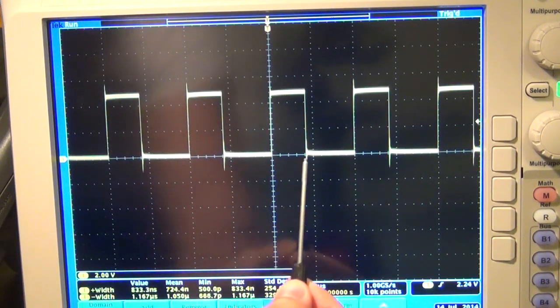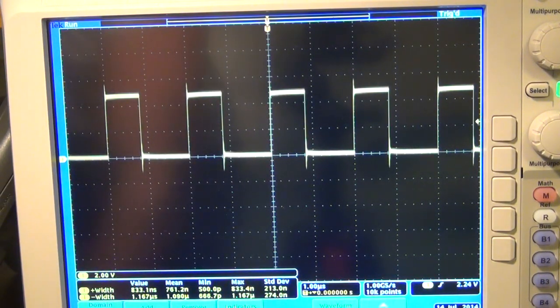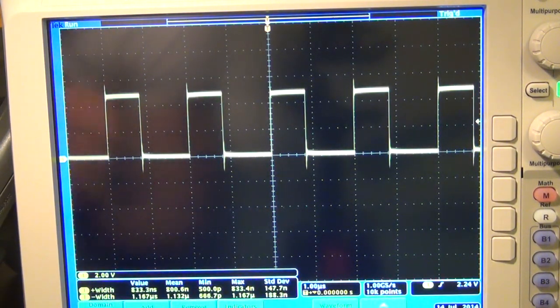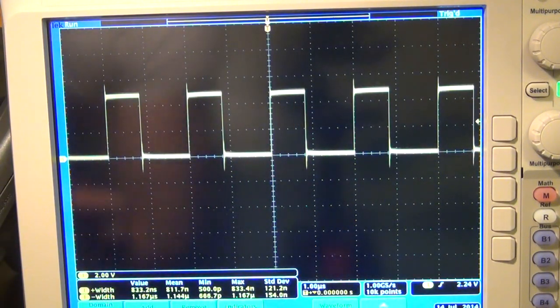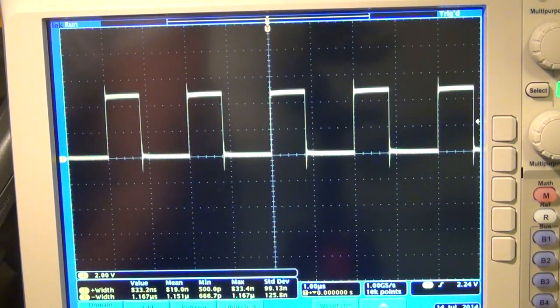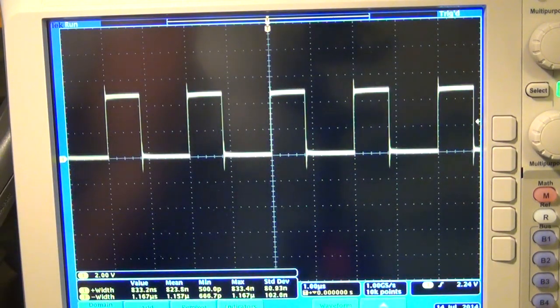It meets that. But the low, again, doesn't meet that. It's about 3 times longer than it should be. But it still works, and I don't know why. Like I said before, I think it's just because the only thing the IC inside the NeoPixel cares about is to make sure that the width of the high period is correct. And as you saw, between the high and the low, I do have the ratio that is required by the datasheet. I just don't meet the ratio for the low portion of the waveform.